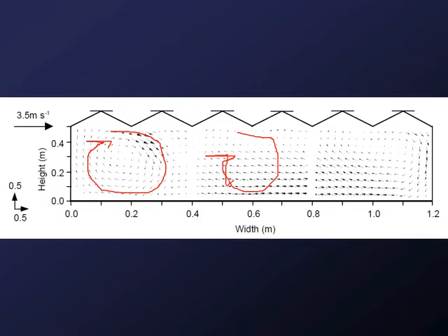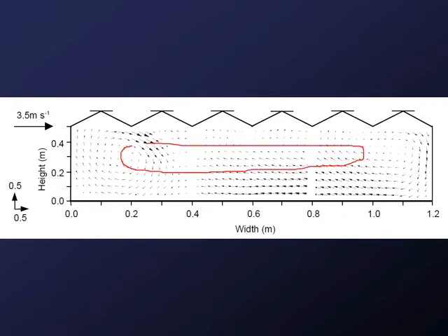This is where having horizontal air fans, so HAF fans, to help distribute the air in the greenhouse helps even out that temperature. So they're often used, although when you have vents above a certain percentage open, the fans shut off because there's so much air movement in and out that they're no longer useful and it's just a waste of electricity.